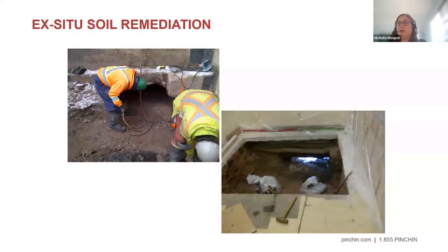Here's an instance where they are doing ex situ soil remediation, but the soil contamination goes beneath the building, so they have to excavate beneath the foundation. And this shows why it's not always a practical method, because this can be very costly, and there are a lot of considerations, such as geotechnical considerations, and you just want to make sure the building is stable, so it can be expensive as well.